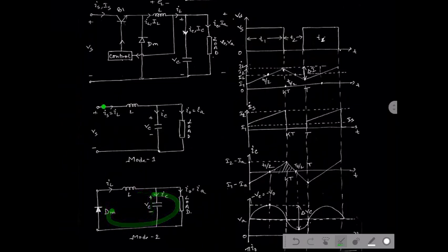That means during charging and during discharging, the inductor current remains in the same direction. And the current tries to discharge. That means the current gradually decreases from its higher value capital I2 to capital I1 in this mode during T2. So this is the operation. The next cycle will be repeated again. We are using the next triggering pulse to the switch, then the voltage appears again, the inductor tries to charge and the current gradually increases for the next cycle.